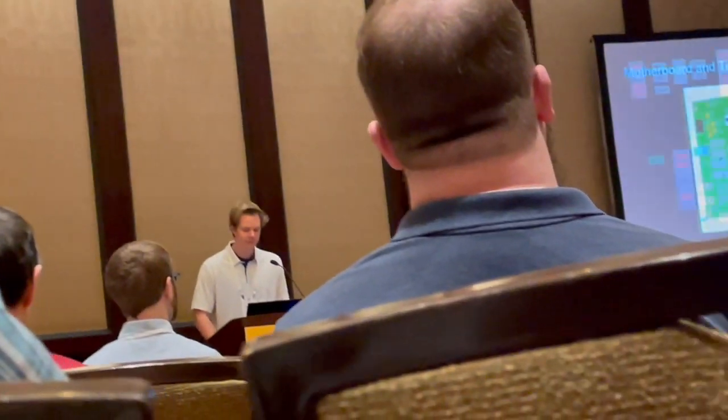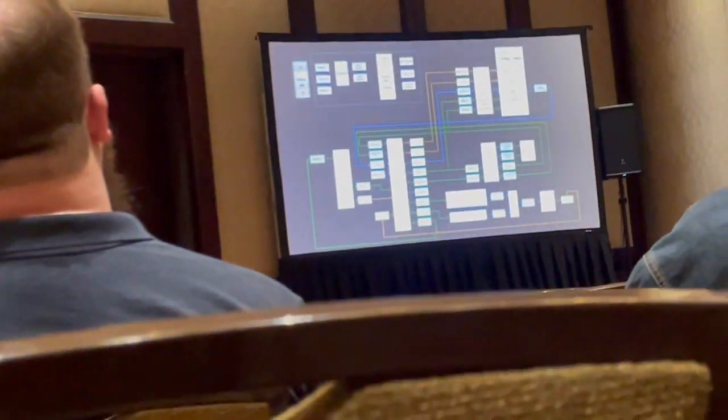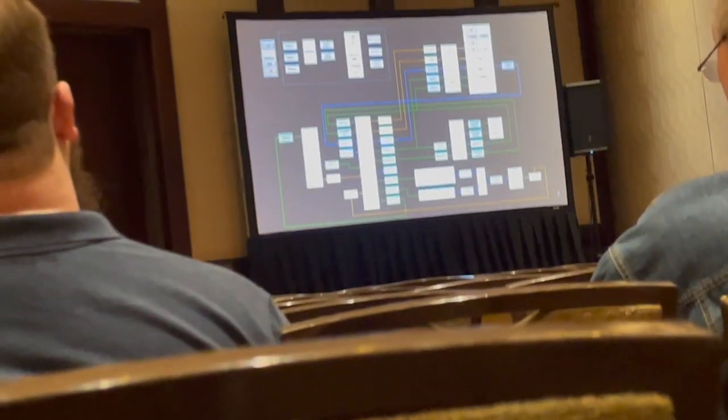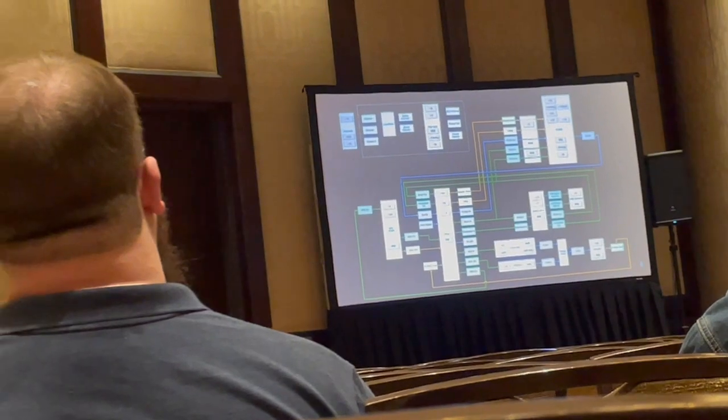And so moving on to our main goal, which was to simplify timing, we had to modify the motherboard a little bit. Originally, we used an FPGA and crystal oscillator to control our timing, and it was shown by this nasty circuit you see up there. We were able to replace that with a GPS disciplined oscillator that we just bought off the shelf from Synergy Systems, and this made the design a whole lot easier and also more accurate.